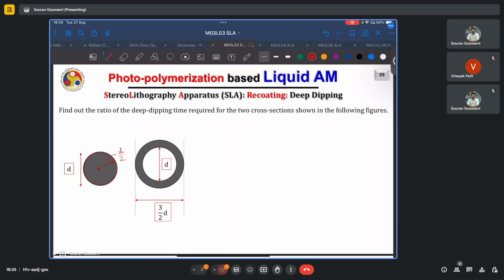We have to keep in mind that for this second case, which resembles a donut, the cross section of a donut, the critical circle is not this large circle or even this smaller circle. Rather, it is the largest circle which can lie in the cross section. It is this. And given that the cross section is uniform, the dimension of this circle will be the same everywhere. It can easily be calculated given that we have the diameter of the outer circle and the diameter of the inner circle, and this can be done. We may also attempt it, say.